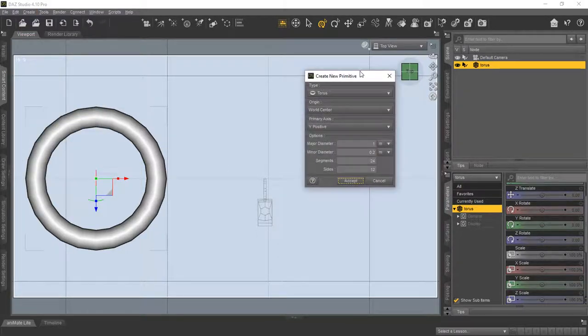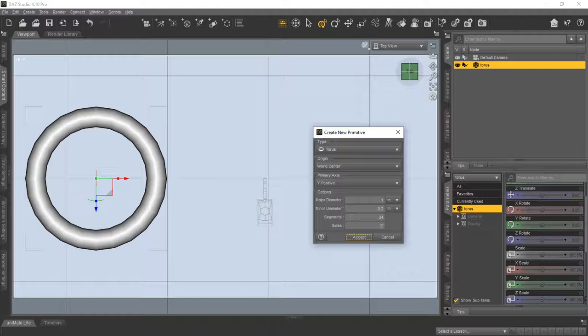This time, though, we'll keep it the exact same size, but we're going to change the number of segments used to define the actual mesh of this torus. So here we'll just go with like 96. That'd be 4 times as many. And we'll go ahead and tighten this up a little bit with, let's say, 36. We'll create that new one.